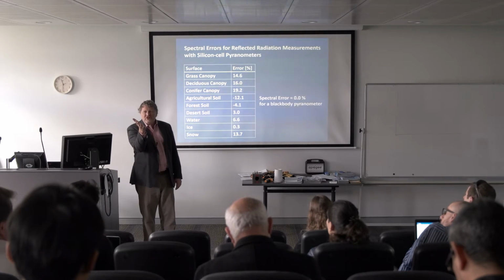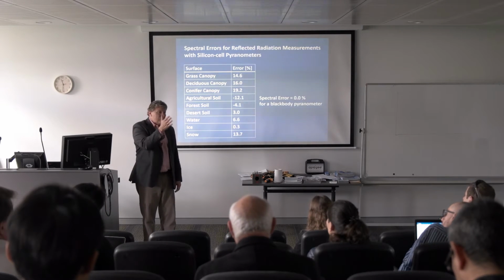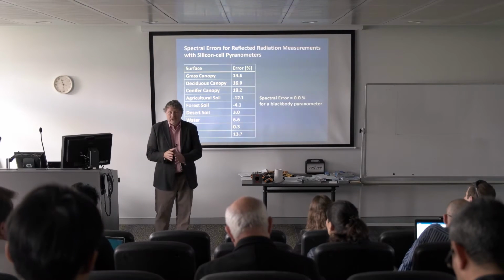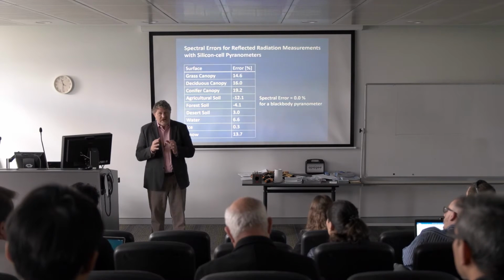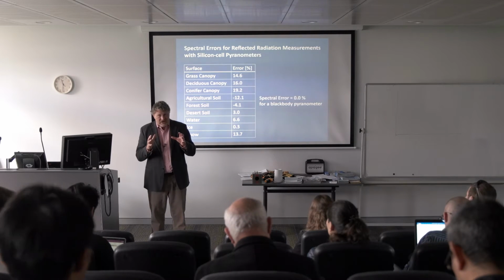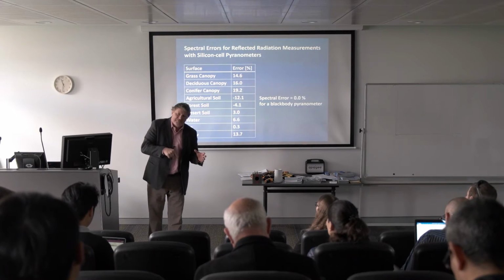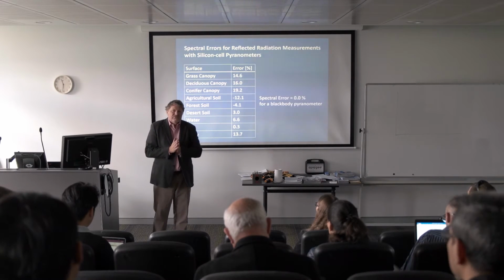And what if the sensor starts to tilt very slightly to the sun or away from the sun? You can quickly get big errors from leveling. So we spend a lot of time making really rigorous leveling mounts, and they all have a bubble level, but now you got to climb in your tower and look at that bubble level to see that it's staying level.